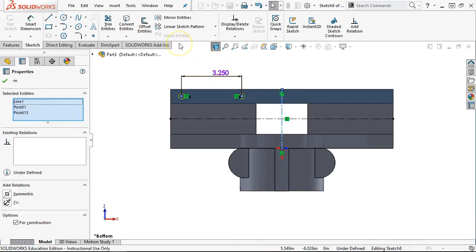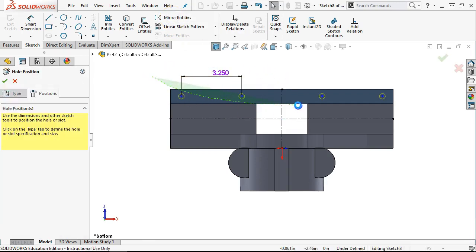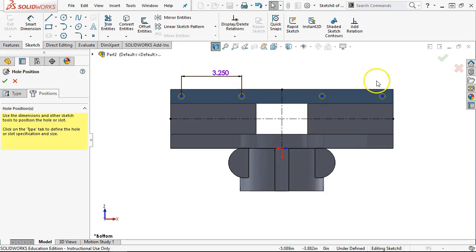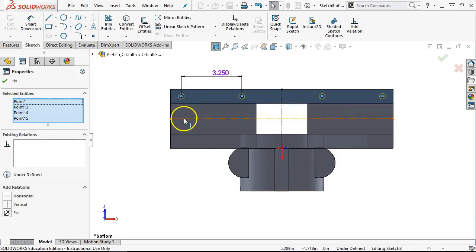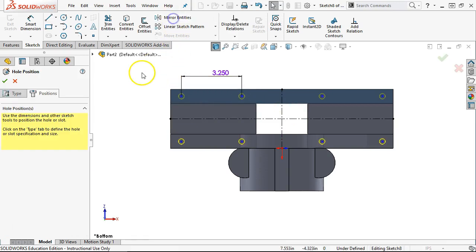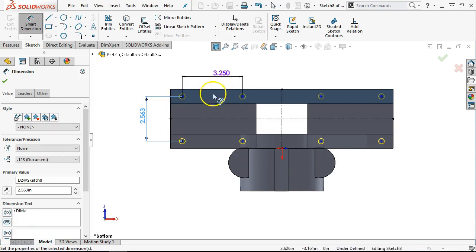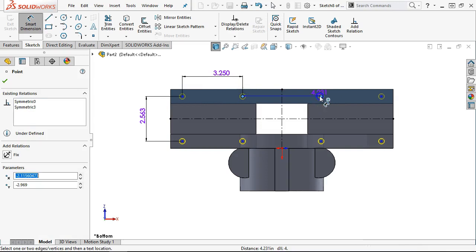All right, so select, Control Select, the 2 points and the center line. I got into lasso, selection tools, box selection. I really want to go left to right so that I don't include the center line. I'm going to pick the opposite center line, mirror those entities. Now I can go in between, which was the 2 and 9/16, 2.563. And then between on the center was 3.5.